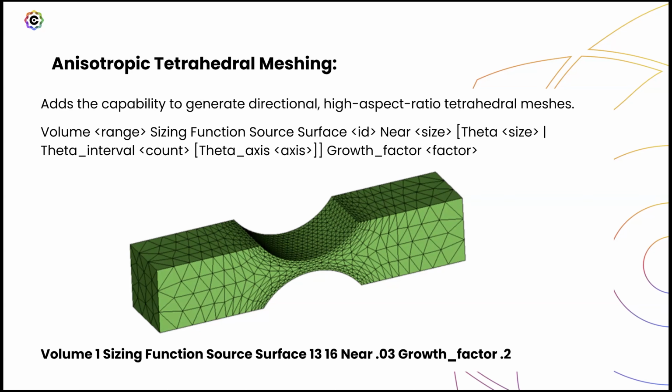In this particular example, they were looking at doing a thermal model, and they just needed to make sure they had lots of elements in a necking area so they could capture that. But the exact shape of the element didn't have to be a perfect tetrahedron for the analysis.